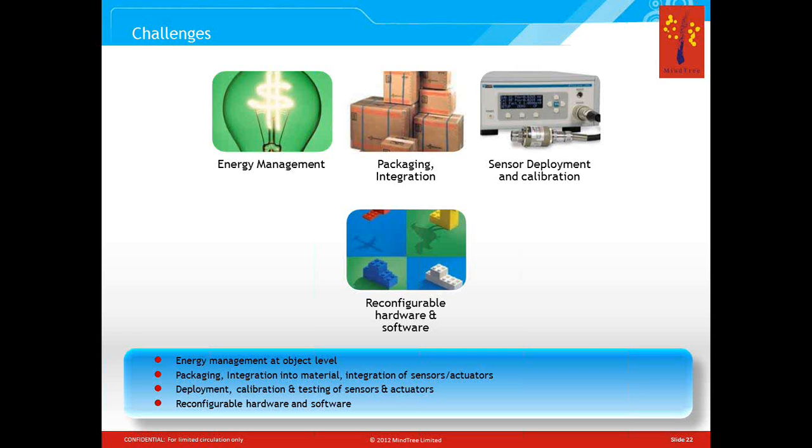Now if you deploy a lot of wireless sensors, for example smart dust, across the field, in water bodies, battlefields or forests, changing batteries is not an option for these kinds of sensors. So those products will have to think about schemes like energy harvesting or energy scavenging, and employ those strategies. An example of energy harvesting is, if you want to put a sensor on a machine, you can design that sensor to derive power out of vibration. So you don't need a battery or grid power. You can generate the power using what is available.